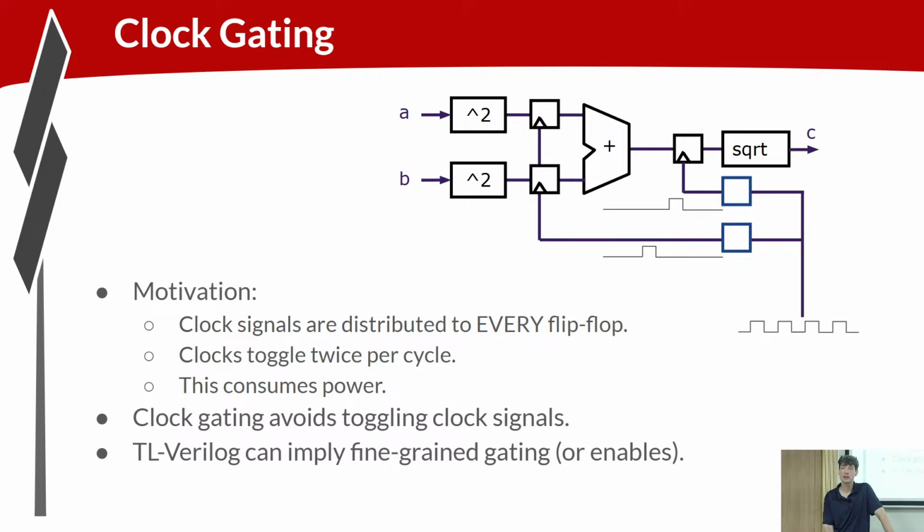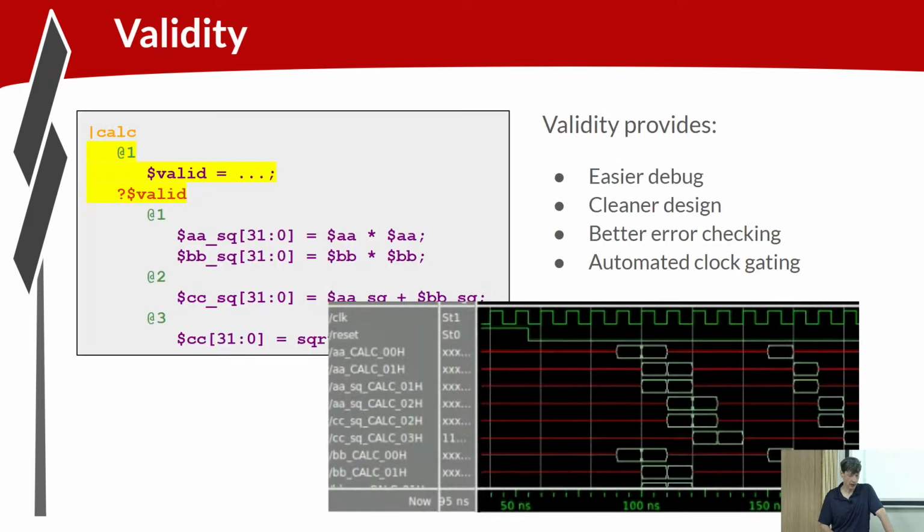Say that last question again. Right. So we know whether it's garbage based on the when condition. So this valid signal becomes the clock gate condition. Okay. So if valid is deasserted, we know this computation is garbage. The designer's telling the circuit it's garbage if it's not valid.